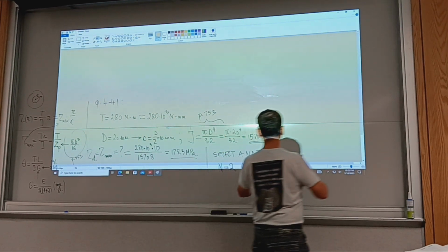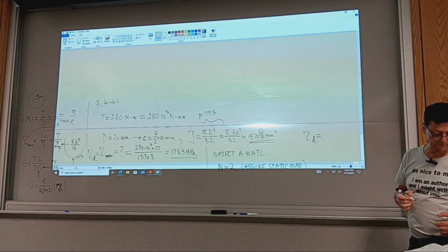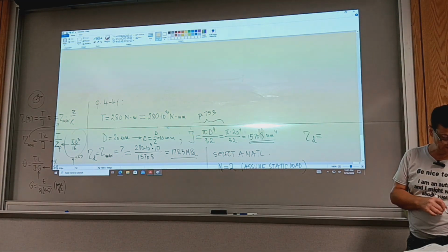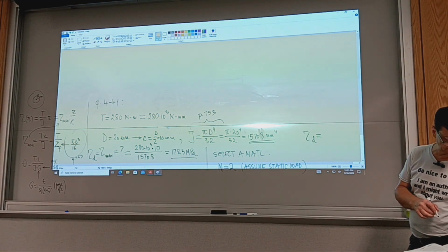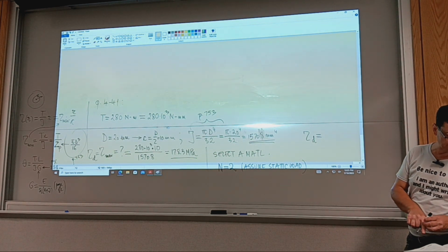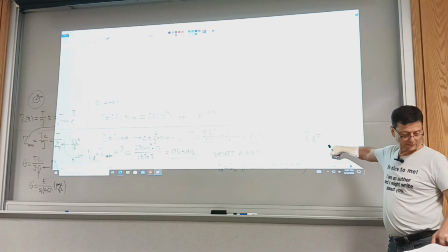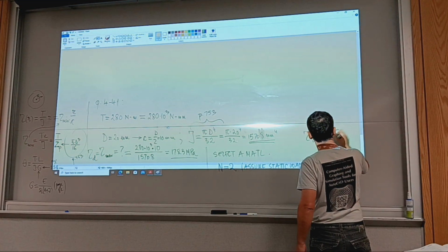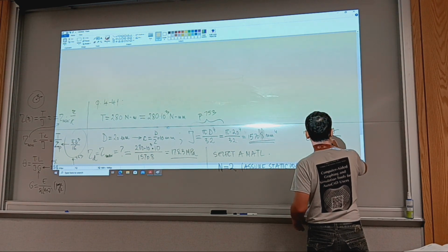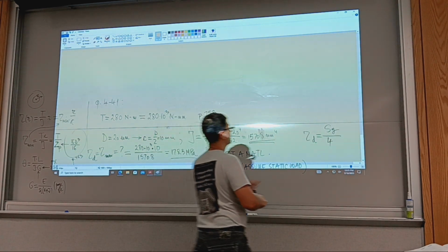And the equation, tau d, is in terms of yield strength, approximated as half of the yield strength in shear, as in the long equation right above where it says tau d equals SYS, yield strength in shear over N, or 0.5 SY over N. So I'm copying the equation: tau d equals SY over 4, coming from 0.5 times N. So it's over 4.